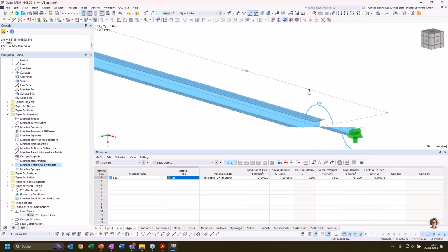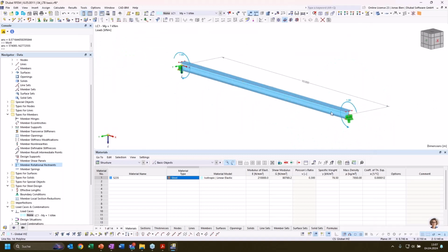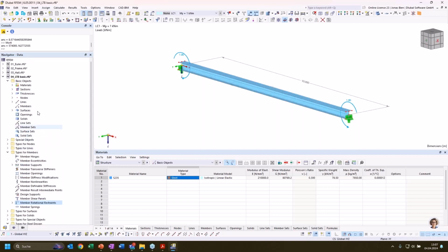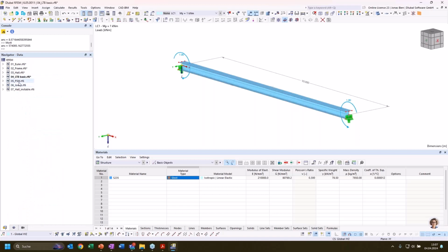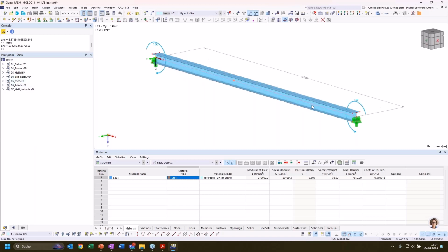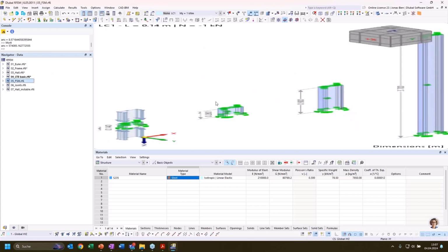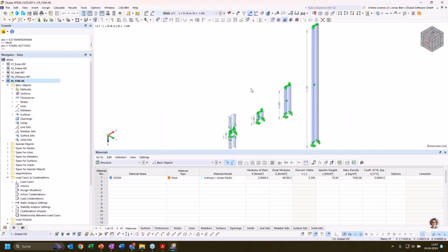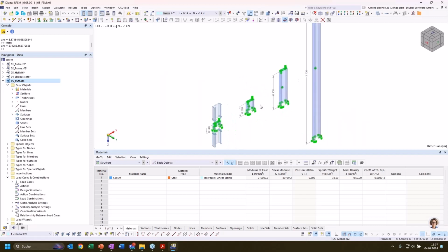And now we could mesh this very finely to do a stability analysis for this shell model. By doing so, we could also analyze local buckling modes of the section. Because it's not very interesting to do it with a hot rolled section that is in this case not susceptible to those local failure modes, I want to do it with a cold formed thin walled section.